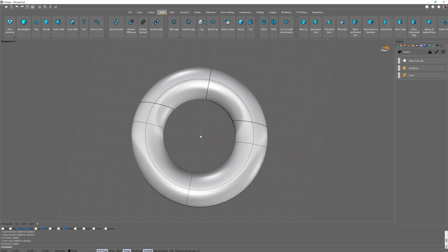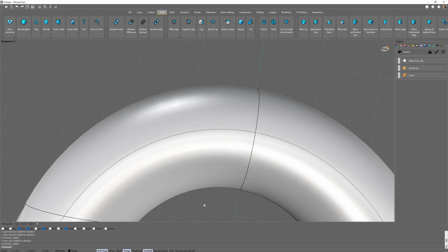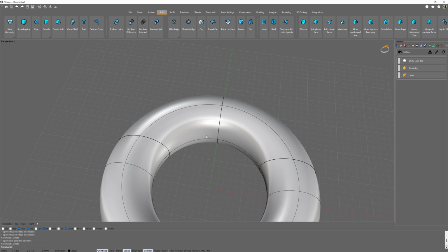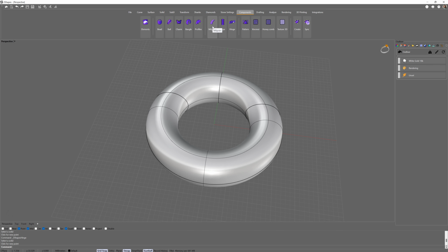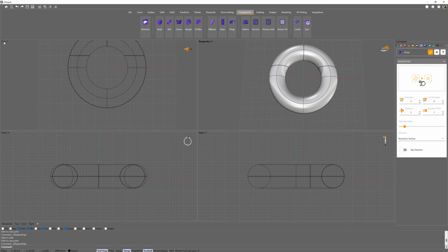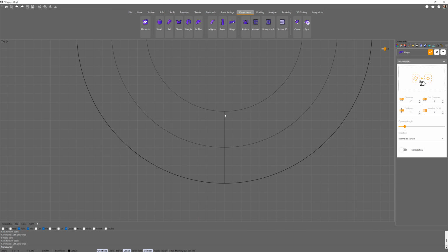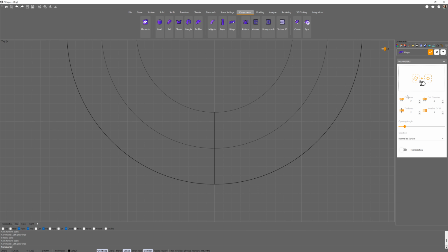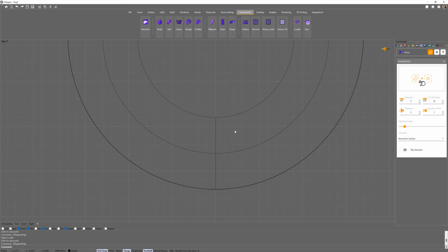It's not necessarily in the middle of the object. Even if you want to split something small here, I don't know. Then let's go to do the hinge. We select hinge, and just a trick, before selecting normal to surface, we will change that in order to be by default. And another point is, for example, here we have, as you can see, 8 millimeters, and the cut diameter must be bigger than that. Then my recommendation is to type something bigger, 12, 16, up to you.